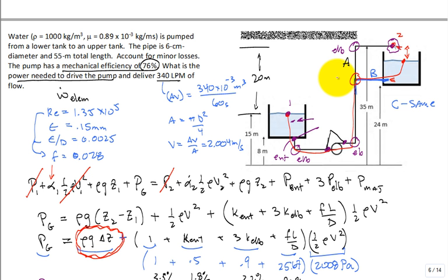The difference in Z. Now, somebody says visually, you didn't give me that number, did you? You needed to give me a number where this came up. Well, I didn't anticipate the question, okay? But I would have probably said this is maybe 32 meters, meaning that there's a 3 meter less lift that the pump has to provide, hence greater flow rate for case B.